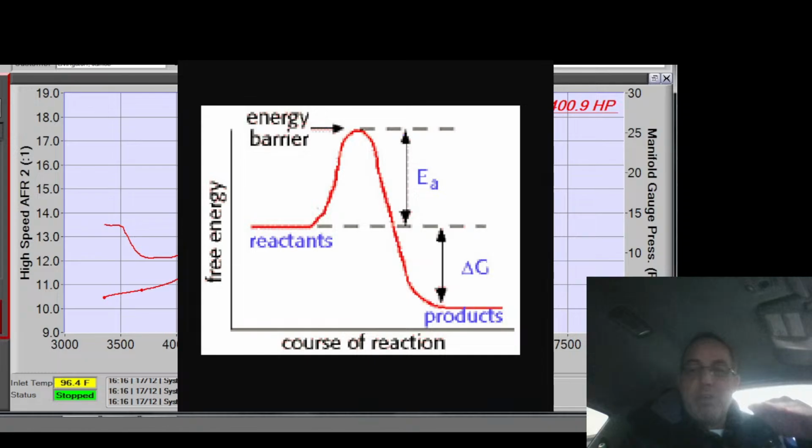A big flat top piston with a big dome on it, down's not going to do you any good, because the piston's only going to move like 15, 20 thousandths by 20 degrees up to the center anyways, right? So that's the shape of the chamber that you're working with. But if you got a big dish below it, you can go down, right? So where that electrode is will kind of dictate what direction your flame front is going to travel in the cylinder.